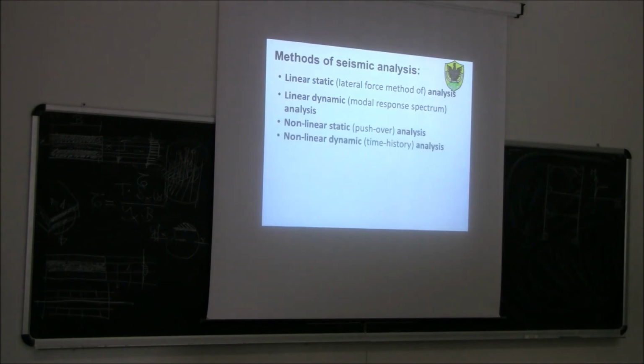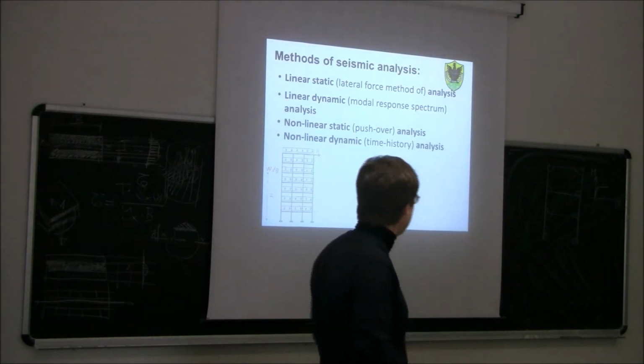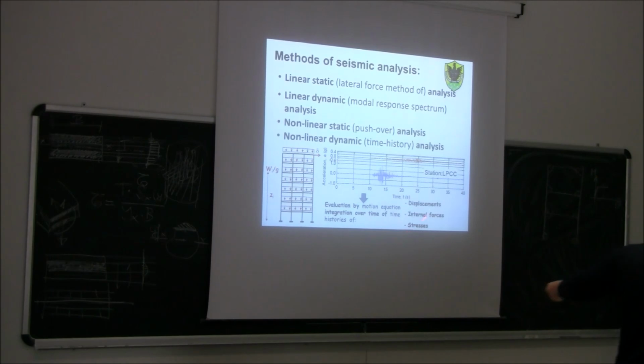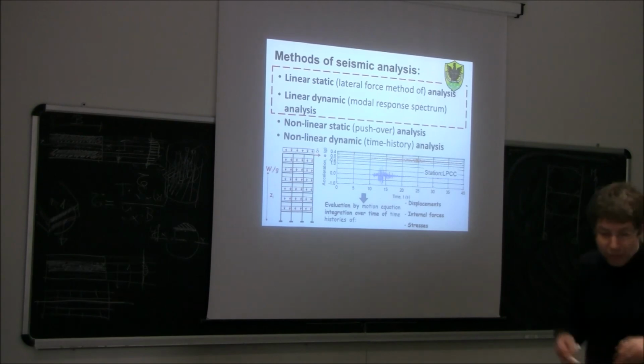And we can also have nonlinear dynamic analysis. Nonlinear dynamic analysis means that with the software we simulate an actual earthquake occurring on our structure. So we have our model, we apply the earthquake at the base of the model, we need to have an acceleration, and we study over time the time history of displacements, internal forces and stresses. Of course, for this course, the most interesting methods are the first two, but particularly